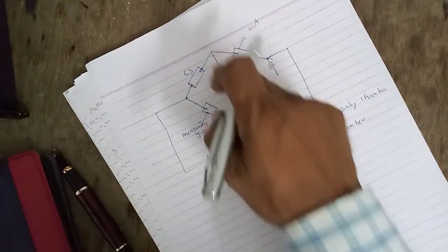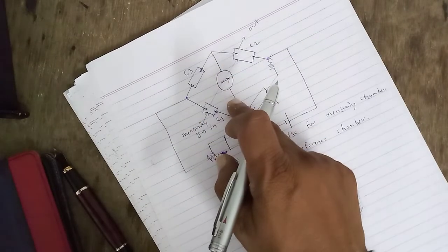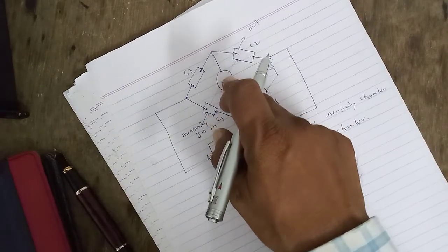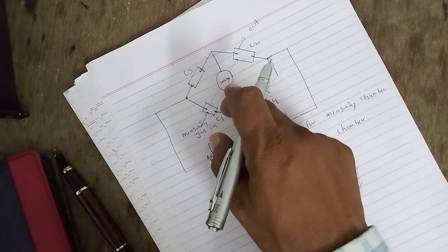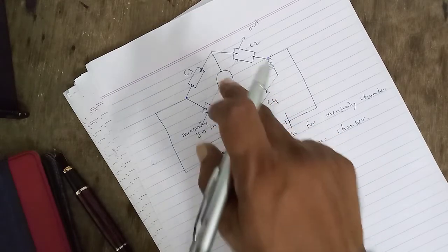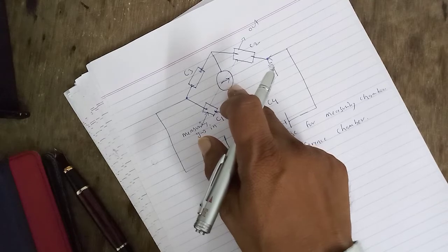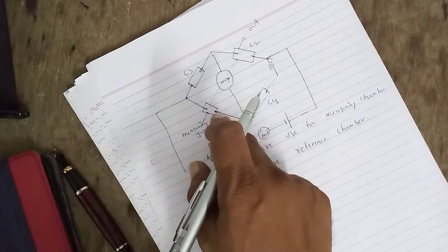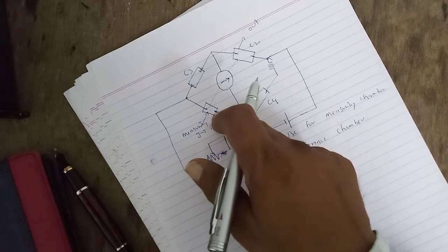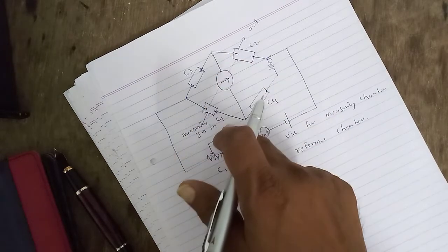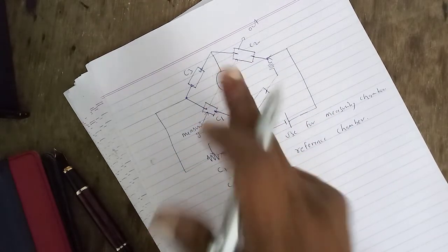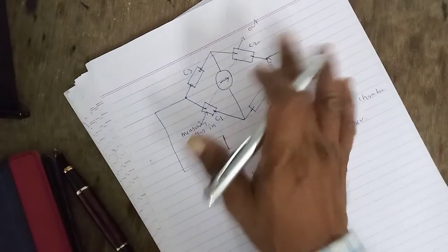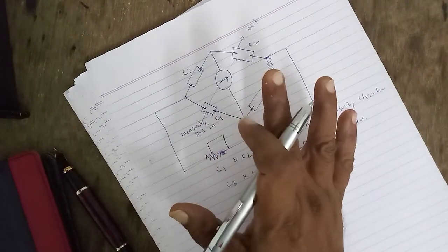This is the zero adjustment, which is indicated with this arrow, and here we have to attach one galvanometer for measuring that particular resistance. When the gas passes through this, it is conducted to the lower part and passes through the measuring cell, where the platinum wire is cooled less. The temperature of the measuring chamber and the reference chamber is controlled thermostatically.